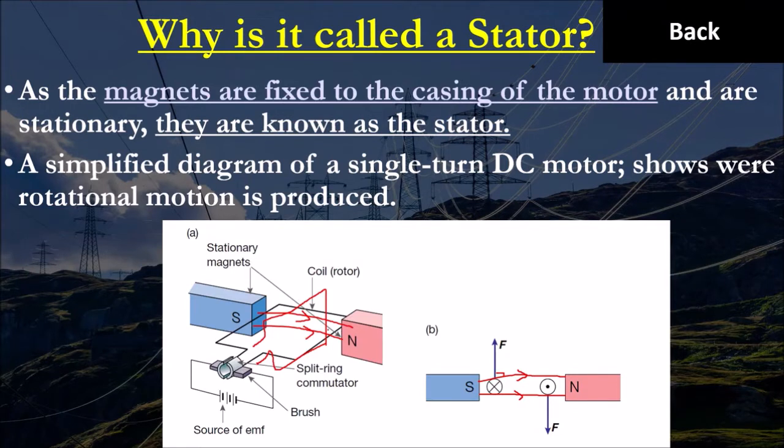So our coil will have zero rotational force. It will have no force either. There's no net force either way. I'll show you why that's the case in a second. Essentially, we have no rotation here, and so it's not very useful. We can't have a motor that loses its force of rotation or has zero rotation. That's why in most motors, you will not see bar magnets used as the stator, because that's not the way to go. It's not very useful.